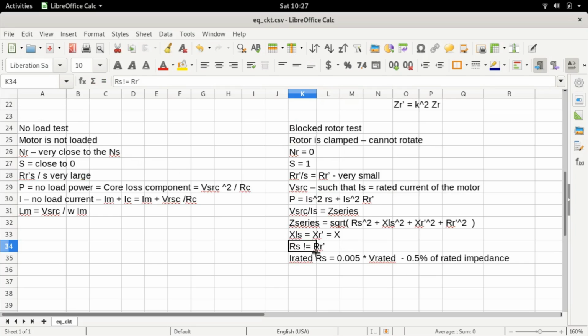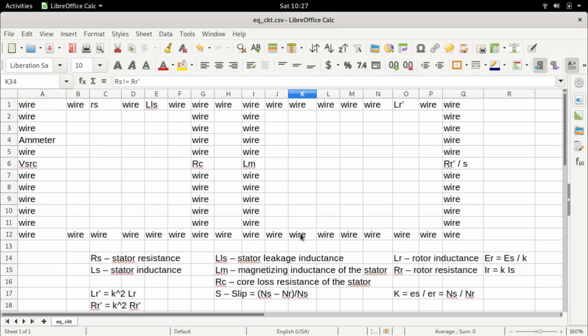Alright, to calculate the stator resistance, and the reason is because the stator winding is a very different kind of winding as opposed to the rotor, which in our case, of course the rotor also can be a winding, but for most cases, like in the case of a squirrel cage induction motor, the rotor just consists of bars, rotor bars that are short circuited on either end.